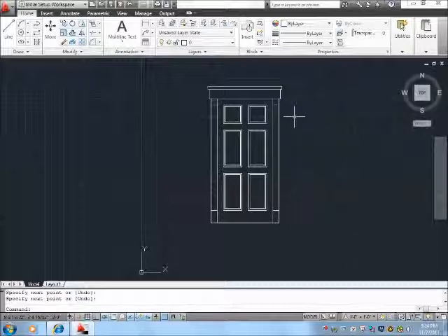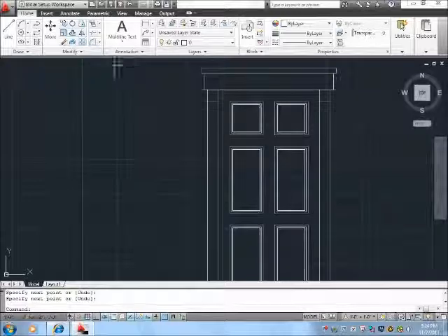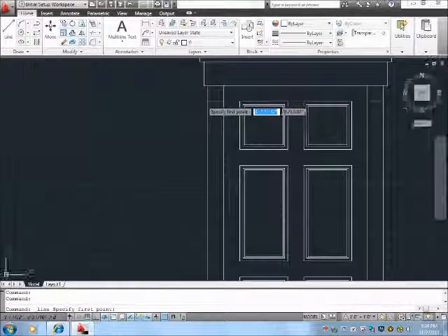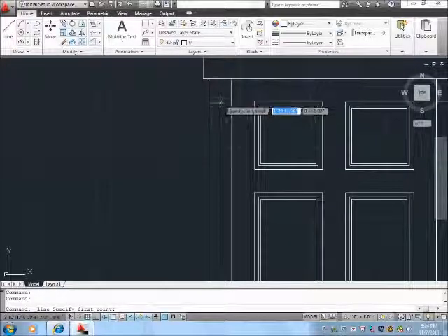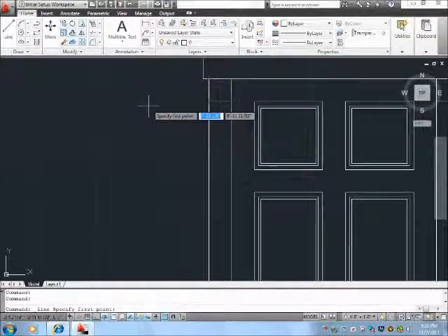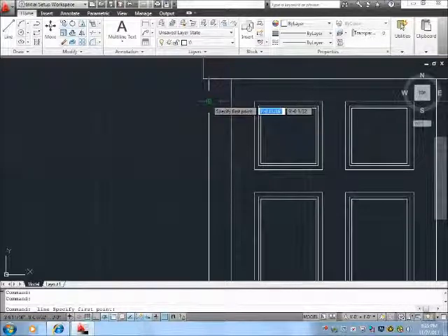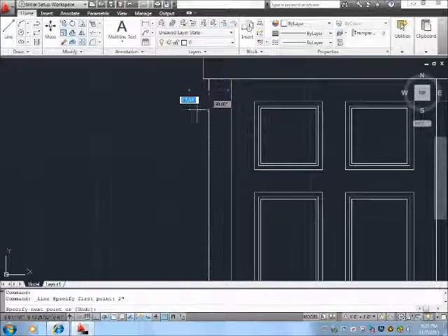We just have to finish off the outside jamb details. So we are going to zoom in on this, come down from this line that was 4 inches away from that corner, come down 2 inches. So make sure you hover over that point that you want to come down from 2 inches for. So come down 2 inches. Ah, see, it didn't end up going right.